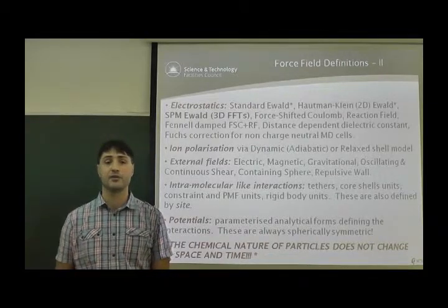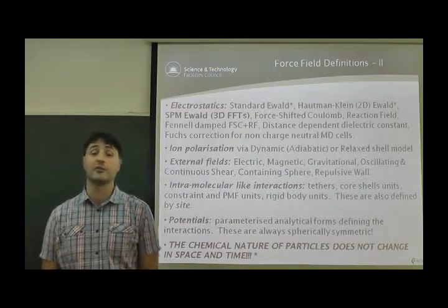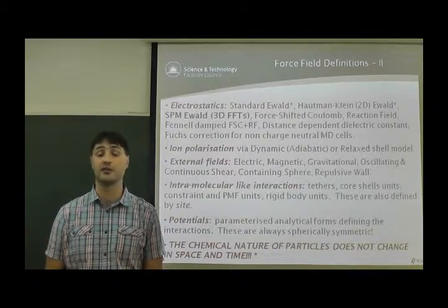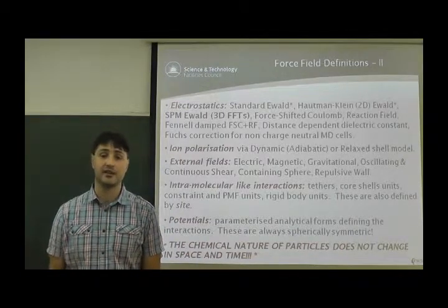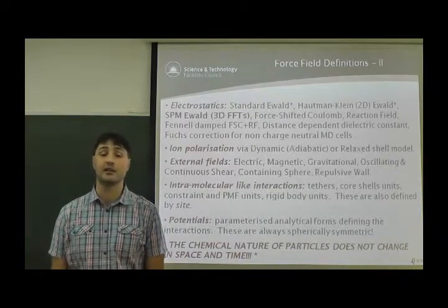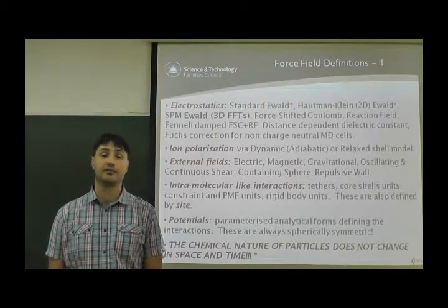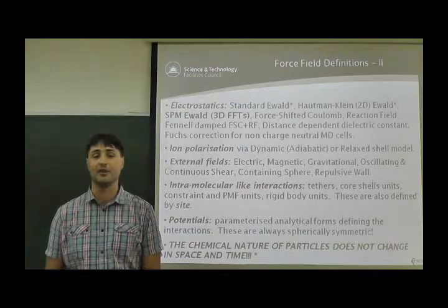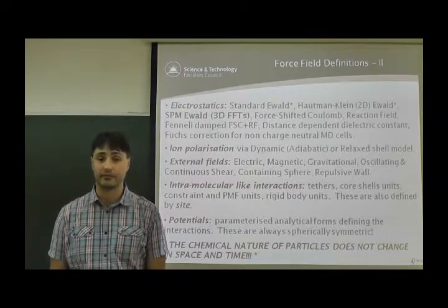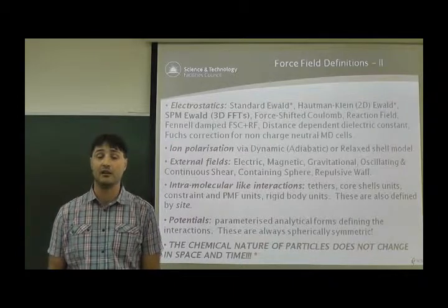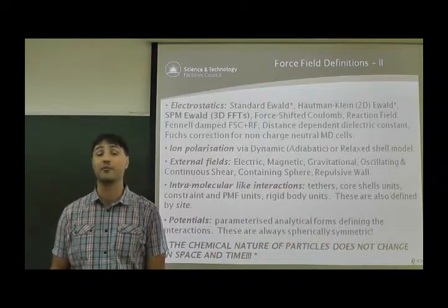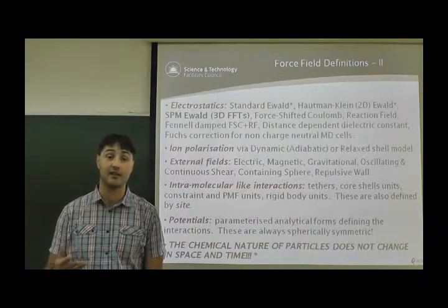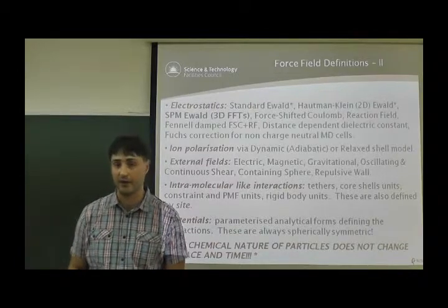Of course, all the potentials for those interactions are provided as various analytical forms within DL_POLY. They're parameterized, and it's the user's responsibility to provide the correct parameters for the specific interactions. And DL_POLY only takes spherically symmetric interactions. There is one restriction on all these entities. We cannot change the chemical nature of particles in space and time. Essentially, what it means is we cannot break bonds or create bonds. Of course, this can be counteracted by specific force fields like ReaxFF. However, this is still not available within DL_POLY.